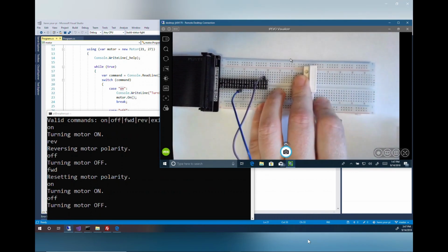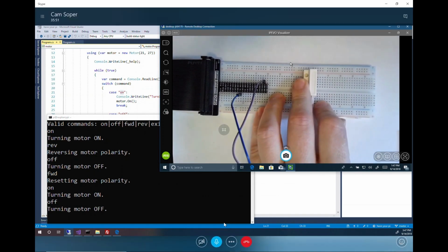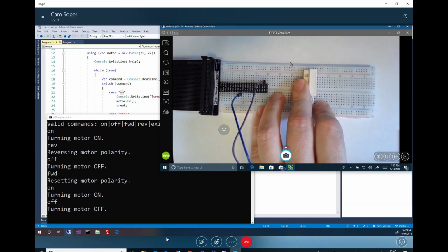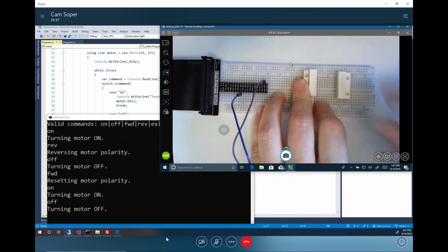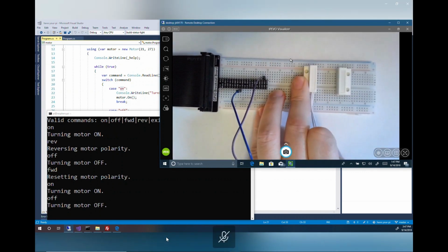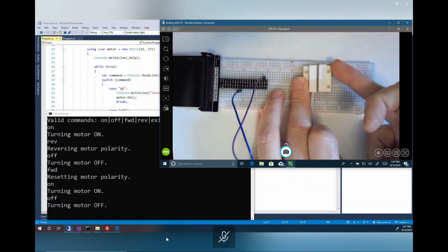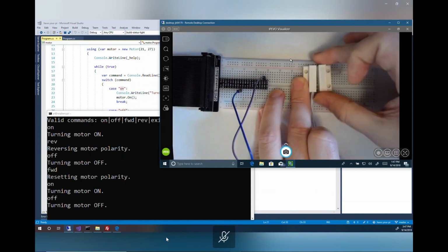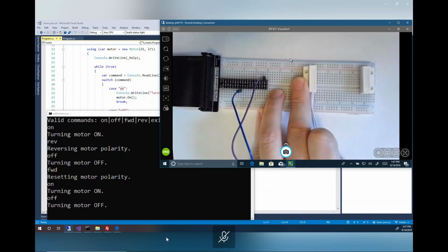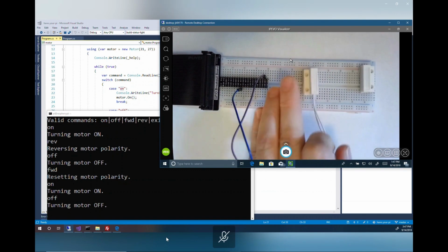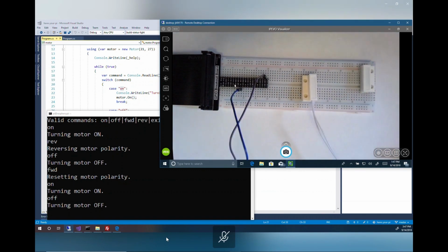So what I'm going to show you now is we're actually going to use pin direction in, right? We're going to watch a circuit to see if it's opened or closed. And what I'm using is this little magnetic reed switch. The whole idea behind a reed switch is when the magnet is present, the switch is closed, so the circuit is connected. And when the magnet is not present, the switch is open, so the circuit is disconnected. And let me zoom in a little bit here so I can show you.